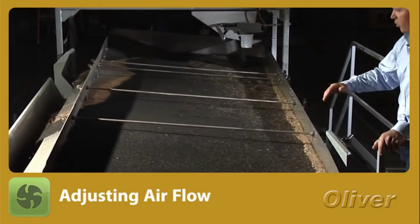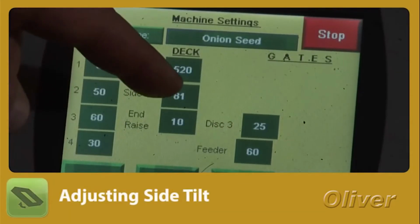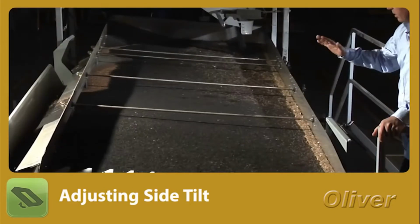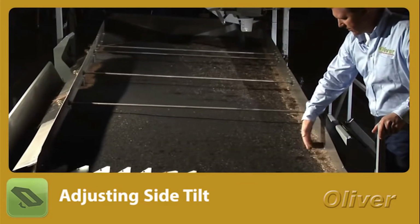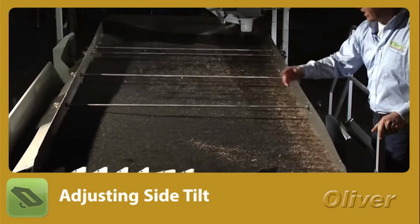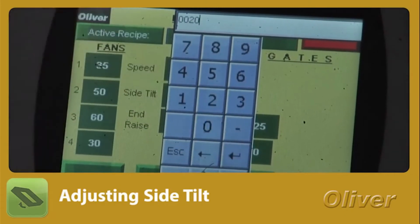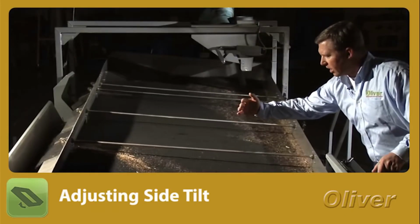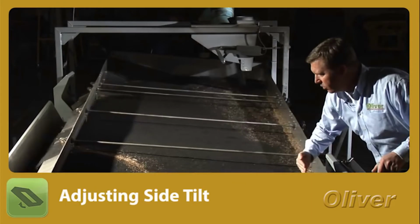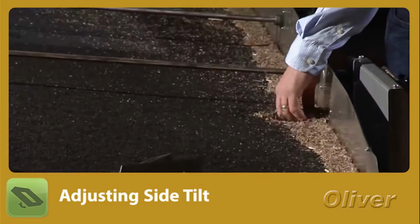The other aspect of quality can be affected by the amount of side tilt that we put on this deck. If I shut the side tilt down to a relatively low angle, you'll see that we lose consolidation of our light product here, and we start to get contaminant back into the good material. As the side tilt is again angled up, the heavy particles will start to come back down and give us a nice even depth of bed across the machine this way, and our light product again starts to consolidate against the rail where we can discharge the contaminant.